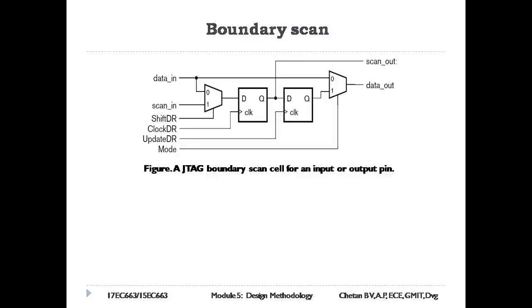The JTAG standard also defines the Boundary Scan Description Language, which is a subset of VHDL used to specify the pins, registers, and instructions implemented in the test logic of a component. We can use a BSDL description of a component together with a set of test vectors as input to ATE for testing the component and the board in which it is embedded.